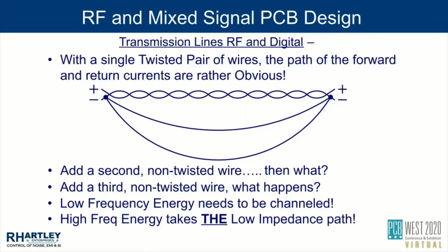I've had many people ask me, why isn't a ground plane a ground loop? Because the places where we use them are at high frequencies where the energy will self-focus. It will focus itself where it needs to be to keep the fields contained. And so we don't have to worry about stray currents going hither and yon. And that's why you don't need to split ground planes in most circuit boards.